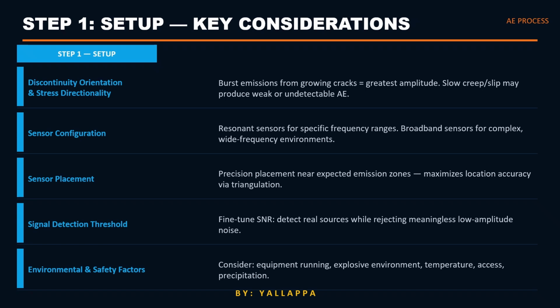Now, in AE testing, good setup is extremely important. Poor setup means poor data. First, sensor selection depends on the expected frequency range and inspection objective. Then, sensor placement must be optimized for accurate source detection and triangulation. Threshold settings are also very important.